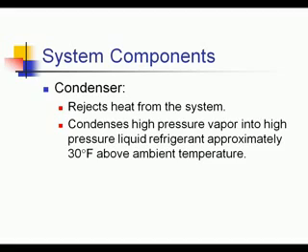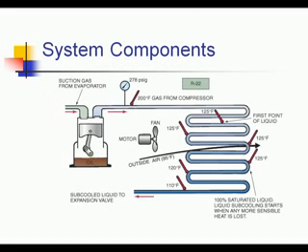You have a basic compressor here. You have the oil on the bottom. You might have a piston. You'll have a flapper valve on the suction side. Suction is the inlet side. You'll have a flapper valve on the discharge or the outlet side. Again, suction and discharge. As the piston moves down, it's going to suck gas in through the suction side. And then when it's full, the piston's going to reverse, push up, close the flapper on the suction side to prevent the refrigerant from going the wrong direction, and open the flapper on the discharge side. And that just goes on and on. But in the meantime, we're raising the pressure on that discharge side.